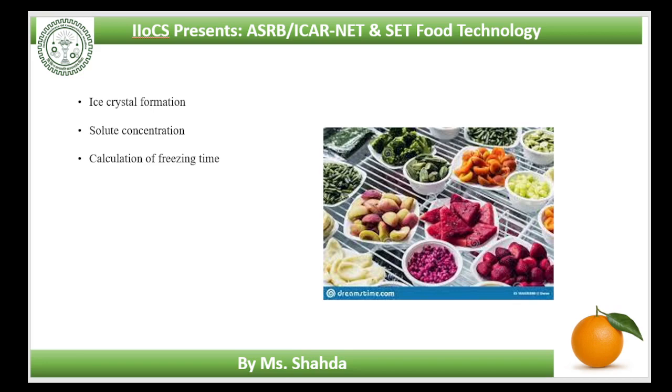During freezing, heat is conducted from the interior of a food to the surface and is removed by the freezing medium. The factors which influence the rate of heat transfer are the thermal conductivity of the food, the area of the food available for heat transfer, the distance that the heat must travel through the food, that is size of the pieces, temperature difference between the food and the freezing medium, and the insulating effect of the boundary film of air surrounding the food. Packaging, if present, is an additional barrier to heat flow.